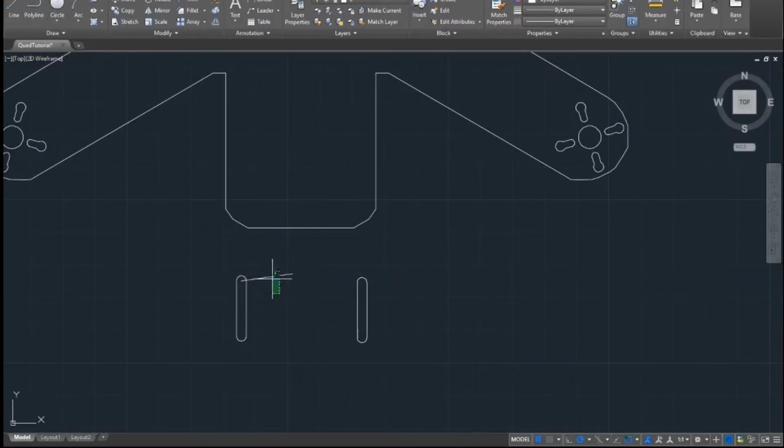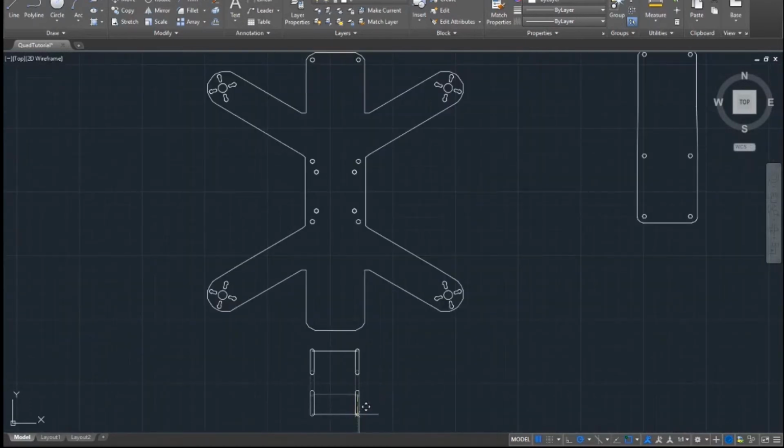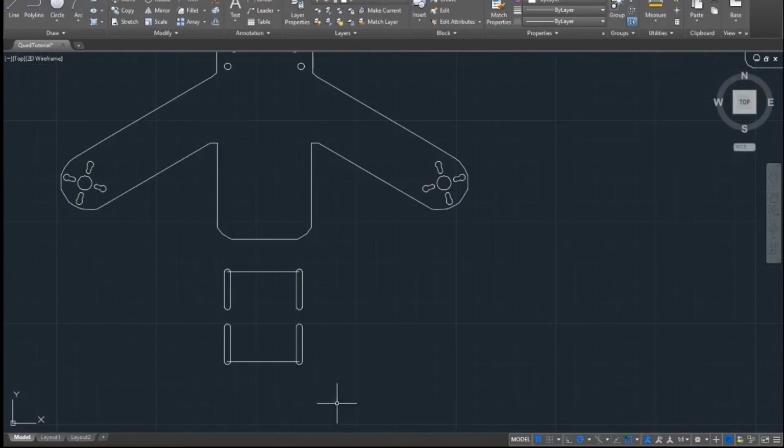Oh no, we're not going to want it. So we're going to want to go for an 18. Actually, sorry, I did my math wrong. So 18 millimeters, and then I'm just going to use the mirror tool just to make sure that everything is absolutely perfect. So mirror that down. I want to hit no, and then we're just going to mirror this object on the axis down. No, do not erase. Select these and move these down. It's going to lock, and then okay, that's a pretty good spacing.